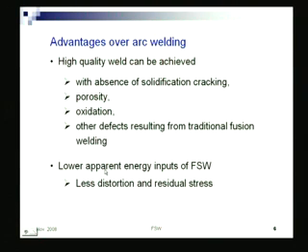And another aspect here is that apparently lower energy is needed, a lower energy input is there, the rate of heat input is less. So, it leads to less distortion and residual stresses, because since the metal is not melting, obviously I am putting in a lesser amount of heat. When I am doing fusion welding, the amount of heat going in is more, but of course, this is not always true, because in fusion welding there can be a situation where heat going in is more, but the rate at which it is going in is less.